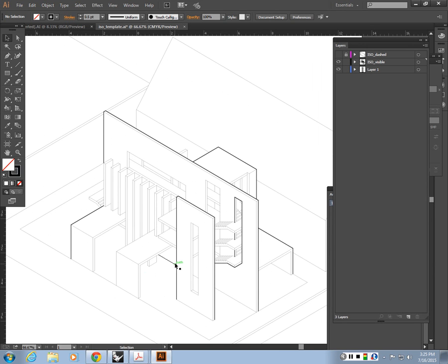Whenever you're applying different line weights, always distance yourself from your drawing a bit to see if you're reading those geometries clearly. In this case, since I applied this outline, look at what I'm seeing. I'm reading this wall better than everything else, so I'm bringing it more visually to the front. That's the intention, basically.